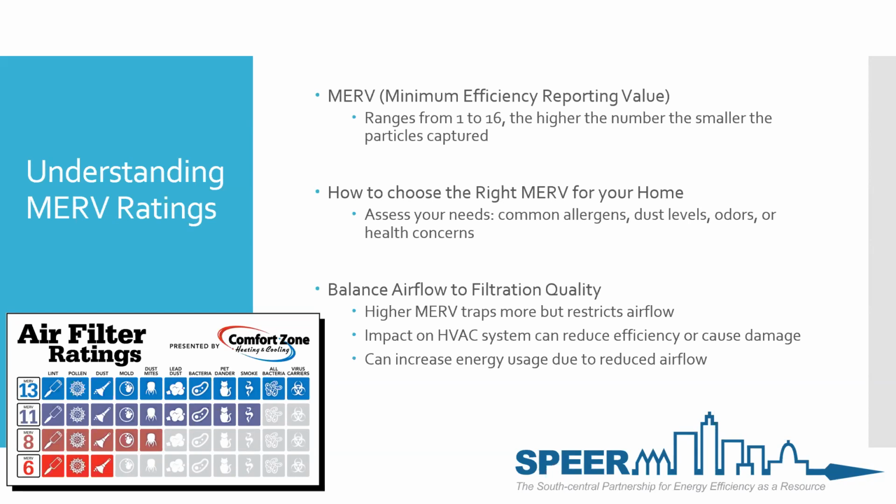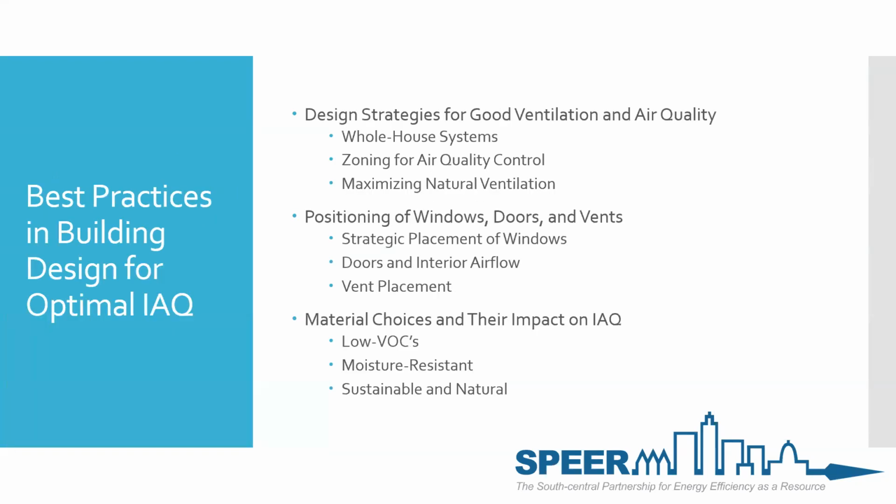They could do a static pressure check and they will tell you that yes, you could, or no, you couldn't, or yes, you could, but you need to make sure you change the filter more times than just once every 6 months. Maybe that's a yes, but your media filter is now every other month. And those things aren't cheap, so that raises the cost of maintenance, but it's those things you have to consider.